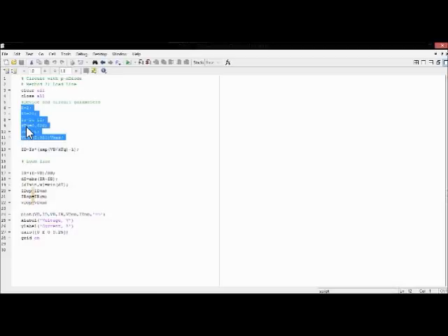And KTQ is given as 0.026, that is kT by q. V max is E, and we have to plot VD, which starts from 0 to V max with a step of 0.001. So we have the diode equation as ID equals IS into exponential of VD by KTQ minus 1, and these are the device and circuit parameters which are given.